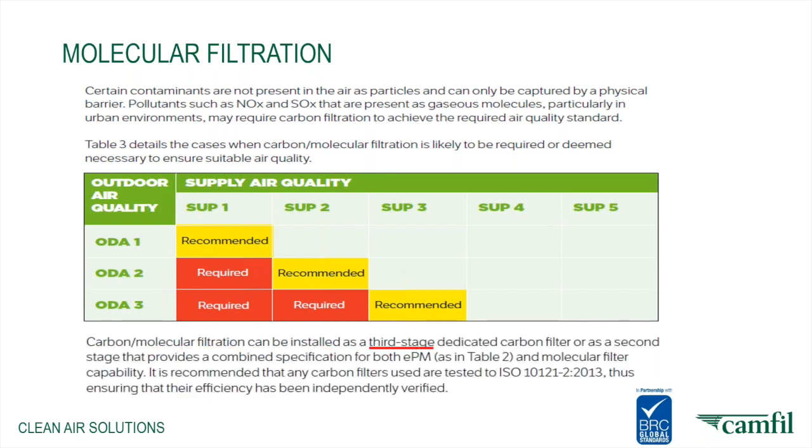What's important to note here when it comes to molecular filters is that they should be used as third stage filtration or second stage filtration. And the reason for this is we need to have pre-filters taking out any particulate that can contaminate the molecular media so that it is utilized correctly. There is no point putting molecular filters at first stage because it will become fouled and will not work.